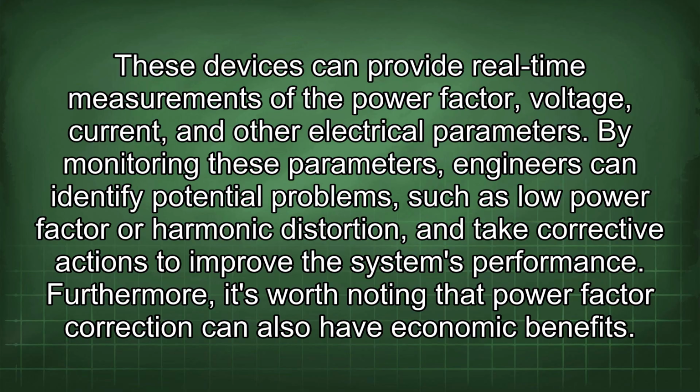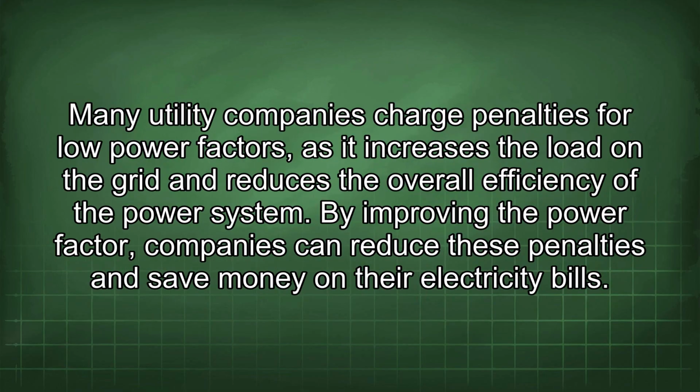Furthermore, it's worth noting that power factor correction can also have economic benefits. Many utility companies charge penalties for low power factors, as it increases the load on the grid and reduces the overall efficiency of the power system. By improving the power factor, companies can reduce these penalties and save money on their electricity bills.